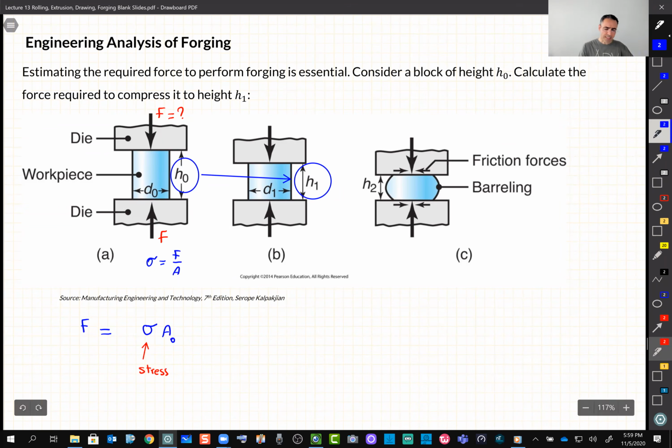So things can get a little bit complicated here, because now we are not dealing with a very simple bar under compression. People have done some study and they add another thing here. They call it KF, and KF is something people call the shape factor. So what it means is people try to apply this formula and test it with the actual load, and